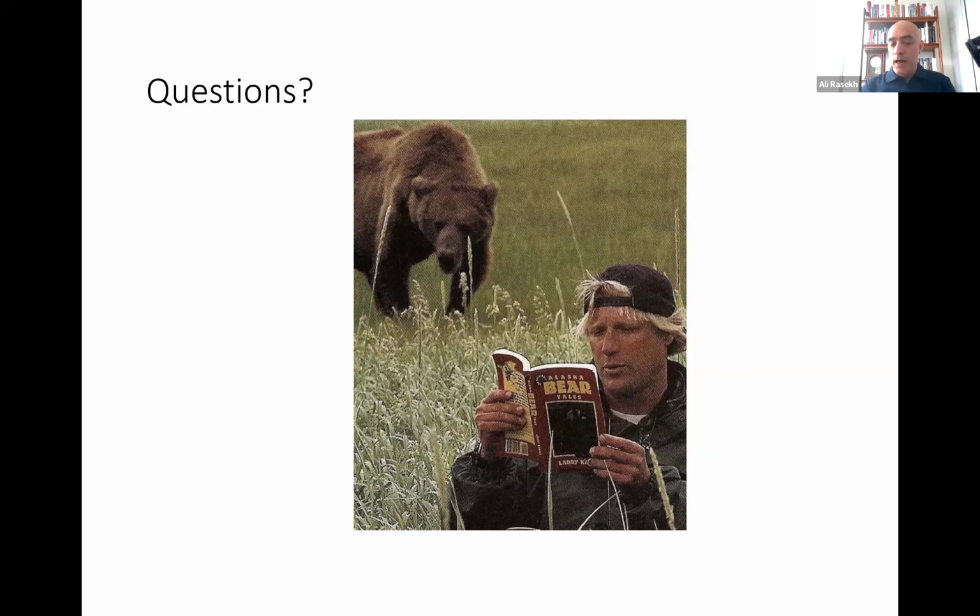And we think, physically it makes sense, that by having a larger model you can reduce the difference between the real modeling and the assumptions that we use. People have done studies and have shown that a large enough model, as I said, 3 times the depth of the dam going away from the dam, makes an accurate enough solution.